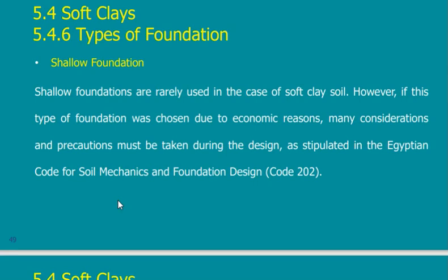Types of foundation. I prefer really this. I prefer to deal, it's either I replace the soil, for me this is very good, or I change the type of foundation. Maybe I go to a better type of foundation that is not affected by the clay. I have, say, 4 meters of soft clay, 10 meters of soft clay, the big amount. I cannot remove 10 meters, so why not put piles to reach the good soil below?